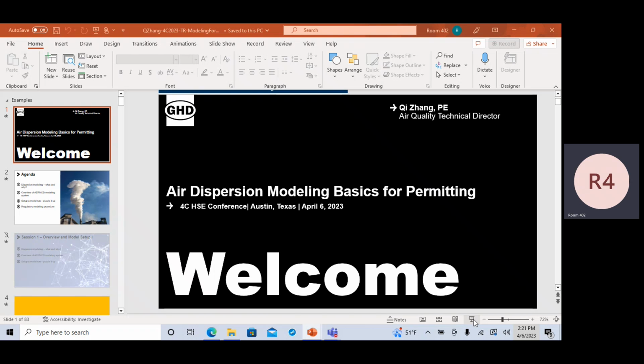But I just got a comment on a project from TCEQ. They say, no, I'm still looking at 1 kilometer. Don't use 3 kilometers. I haven't discussed with him yet, there is some discussion we can have, but I'm not exactly sure on this, because I used to think, since AERSURFACE allows you to give a user input radius, why do you have to lock it at 1 kilometer? Why is the size so big?